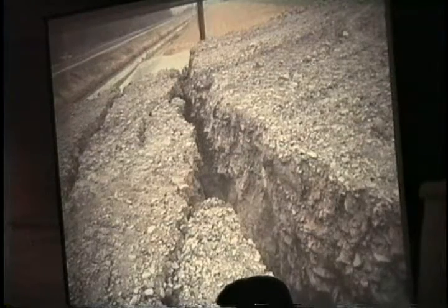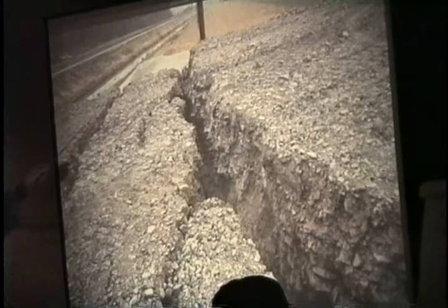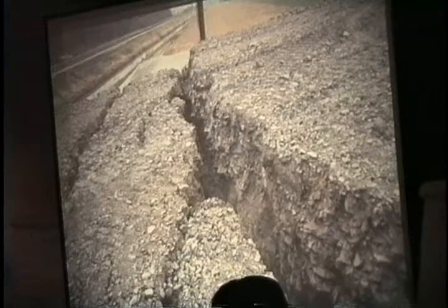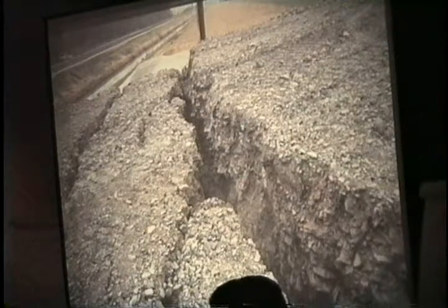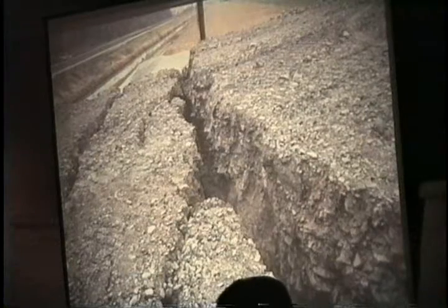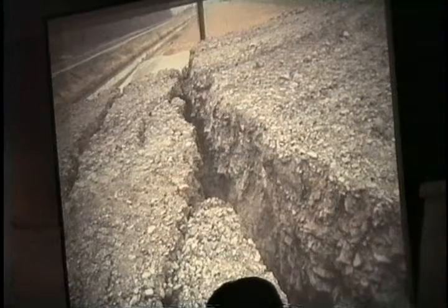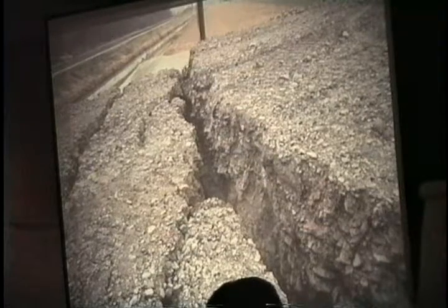The bridge was being expanded. This was the embankment, and you can see they had a bed of improved material. What they did is they dug out shallow clay shale material, and like 30 feet down was black shale, which was very competent, but they never went down there.